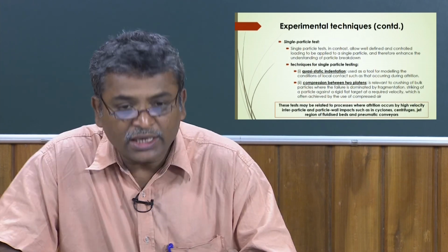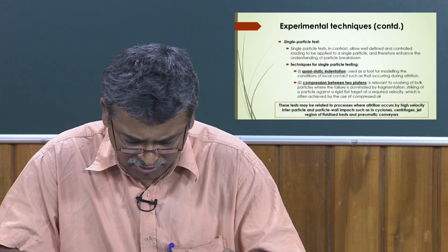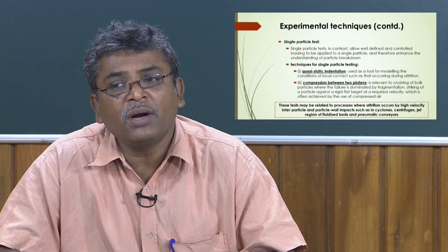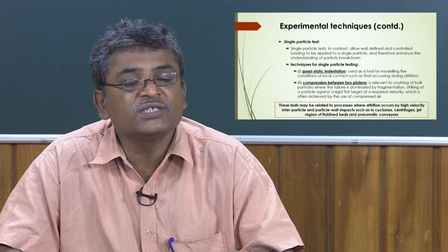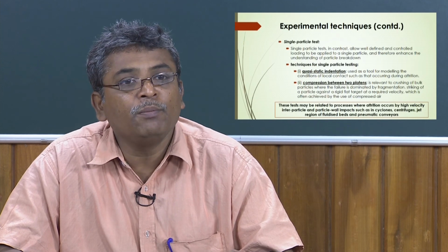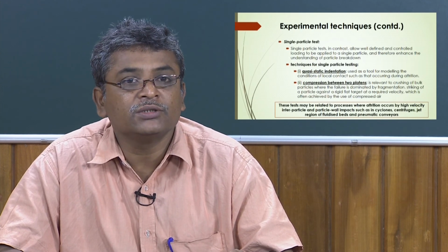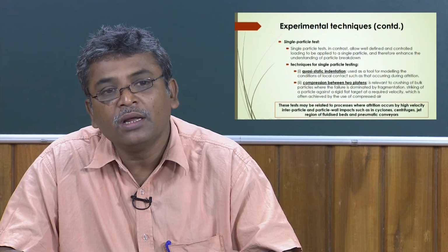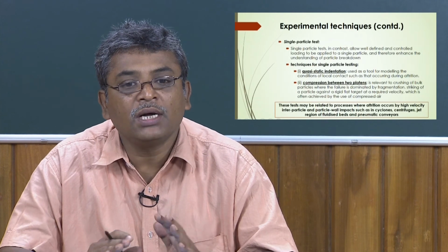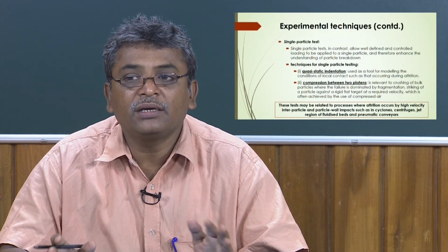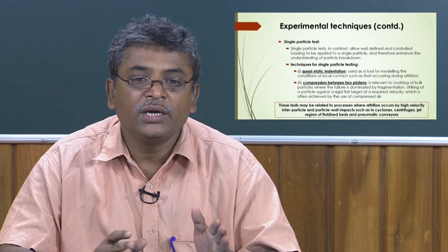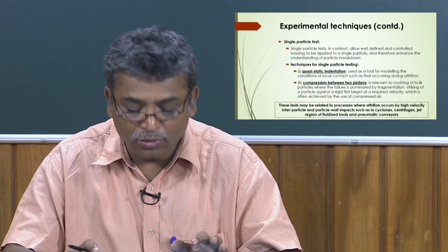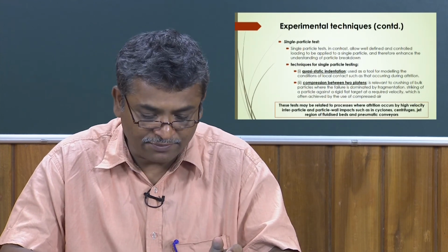So, this attrition depends on energy, and there will also be some wall effect. Of course, if the particles have a smooth surface, then attrition will be less. If the surface of the particles is rough, then attrition will be more, because the collision and interparticle hitting of the surface will be more intensive than on a regular surface.